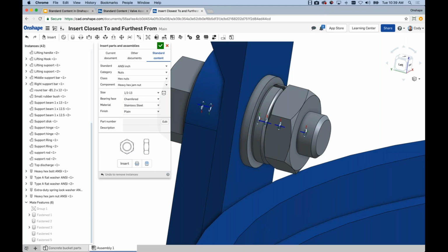So, is it furthest from the latest part introduced? I'm thinking of a grounding stud, which would have a series of plain, sprung, nut, in this order. It would be furthest from the face selection that you make. So you would want to make a face selection on the furthest part out, in your example.